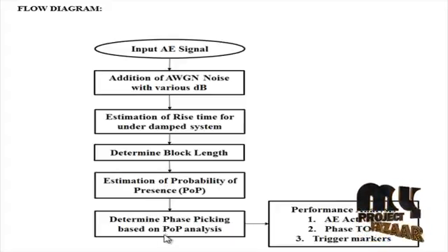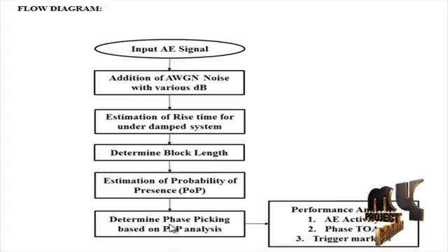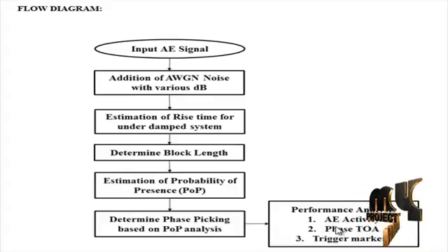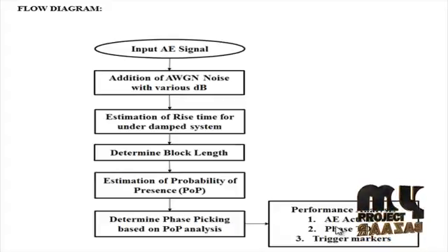Then the time of arrival. TOA estimation requires enhancing the time domain resolution of the channel response in order to resolve the paths and enhance the accuracy of estimation. Compared to the TDOA technique, time of arrival uses the absolute time of arrival at a certain base station rather than the measured time difference between departing from one and arriving at the other station. The distance can be directly calculated from the time of arrival as signals travel with a known velocity.